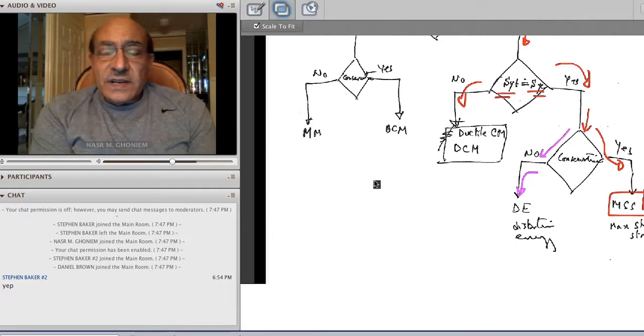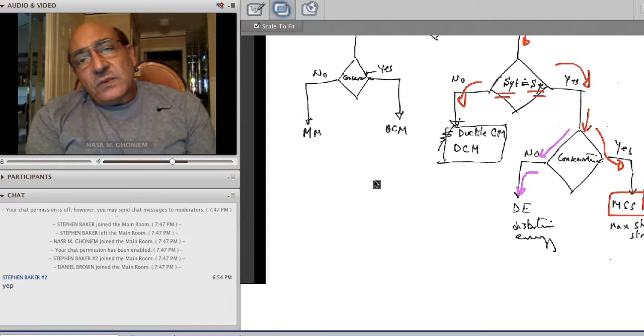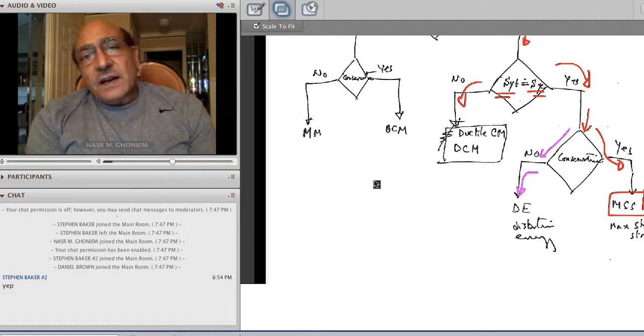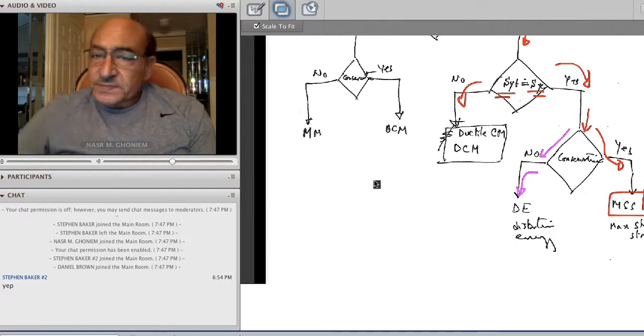Now, for most of the codes like COMSOL, when you interrogate it, you'll find that you can plot pretty much the distribution of every component of the stress tensor everywhere. But for failure, it's much easier to select a representative, which is the equivalent stress or the von Mises stress, and then compare it to the yield strength of the material. That's the easiest approach to determine if you have yield at the point.